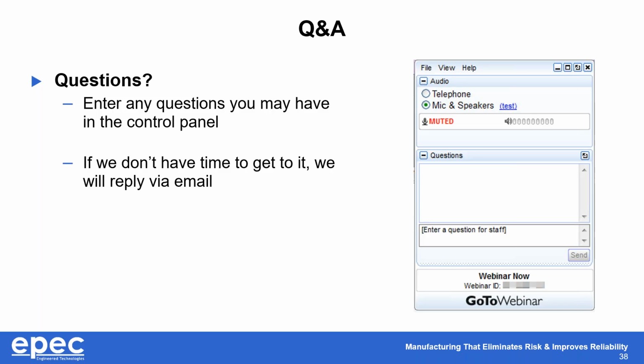As we look at the impedance values in our PCBs and we develop the layout and the routing, we know where to place them, we know the length of them, and we also know how to test them. So impedance testing of the circuit traces, if it's not correct, we'll know at production manufacturing. And running the test values at design, routing, and layout gives us the room to make changes.